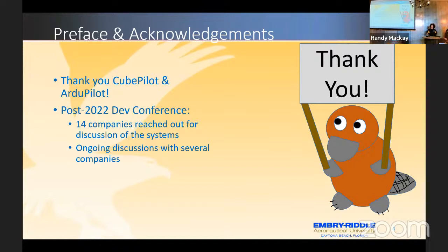Yes, Paul? The question is, obviously if you have a two-lane system, how do you know that one lane's fine? Making a switch over and switching over doesn't get it. I think you alluded to that, and that's been done by the triplex with median select, which is mathematically guaranteed to be robust to a first failure.